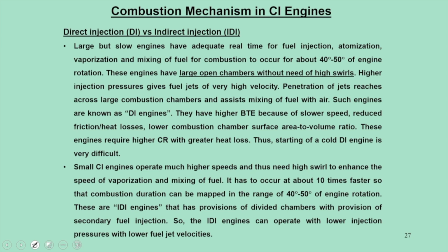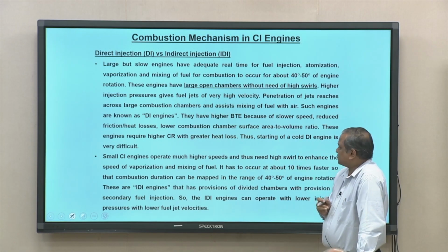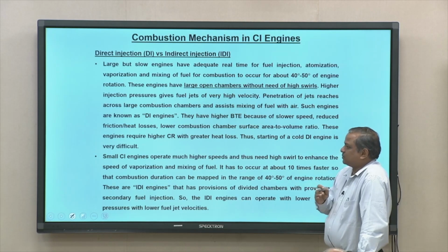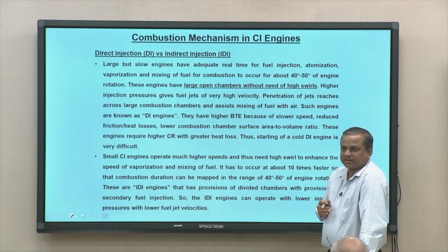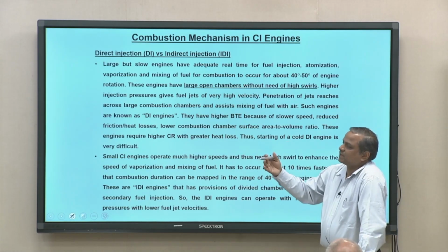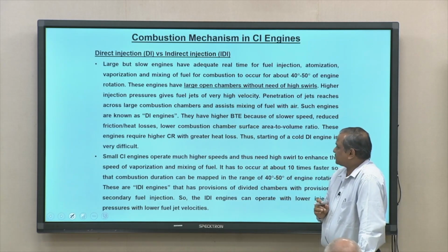But when you look at an engine cylinder with a small compression ratio, although we are going for compression ignition mode, the area is not sufficient for us to create an environment favorable for combustion, because the fuel doesn't travel as a jet for a long distance; rather it terminates at a short distance, because it sees the smaller volume in the engine cylinder.